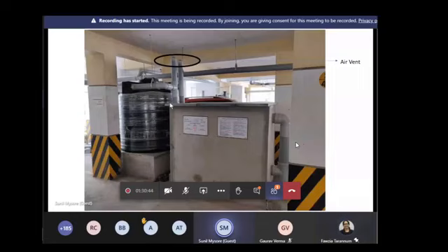I think I did mention why you have to use it. If you use a T junction, what happens is, because you are putting this valve on a vertical section, water is flowing vertically down. When you look at the cross section of the pipe and the water is flowing, the water will be sticking to the walls of the pipe. The reason being the surface tension property of water. So if you have a T joint, in a small drain, because of surface tension, a little bit of water can get into the T and go further laterally than flowing down. That is why we use a Y joint.